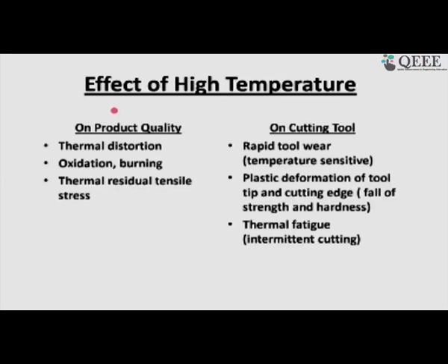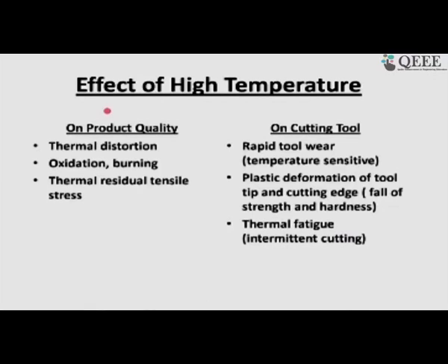So, it is an interrupted cutting. So, you have a cyclic mechanical loading and also cyclic thermal loading. When you put them together, the effect is severe and the tool is affected by this thermal fatigue. So, at least we understand that protection of the tool and protection of the job means controlling the temperature.